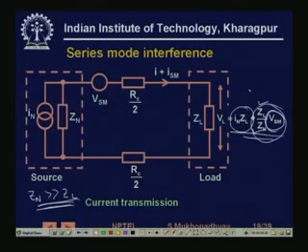So this is one of the reasons why this 4 to 20 milliampere current standard has been so popular. It makes a lot of sense to transmit instrument signals in the mode of a current.